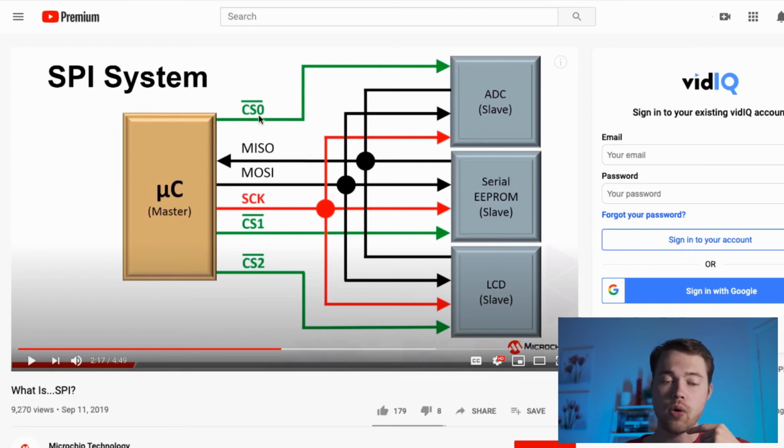If you set all of them to 0, which is very unlikely to happen, then each one of them is going to think that the master is talking to him. They're all going to receive the signal and try to decode it, try to understand what that signal means, and reply using the other wire, and that's going to become a problem. If they all try to reply at the same time using MISO, master in, slave out, you'll get completely unpredictable behavior.